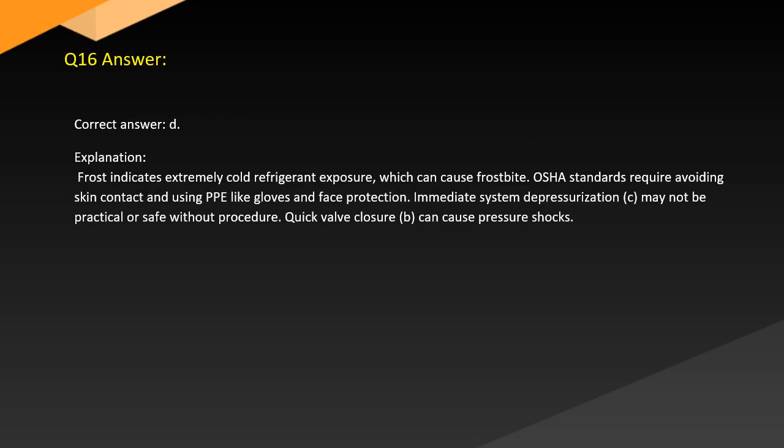Answer. Correct answer: D. Explanation: Frost indicates extremely cold refrigerant exposure which can cause frostbite. OSHA standards require avoiding skin contact and using PPE like gloves and face protection. Immediate system depressurization, C, may not be practical or safe without procedure. Quick valve closure, B, can cause pressure shocks.